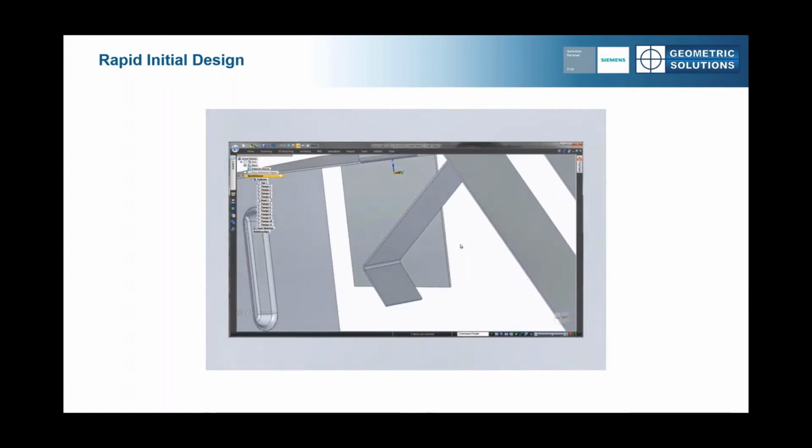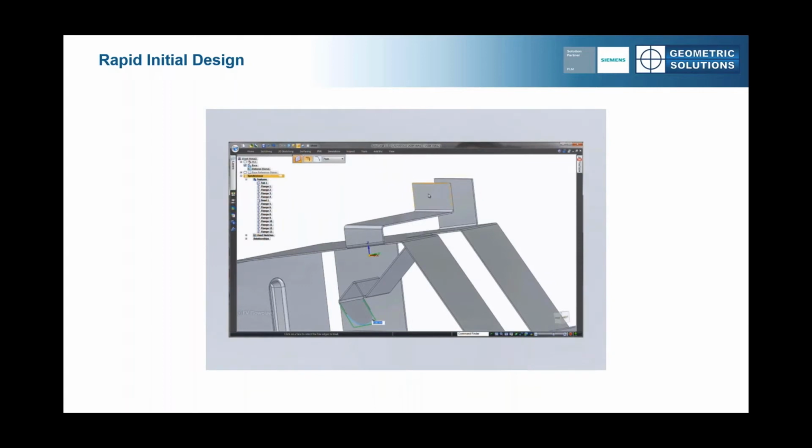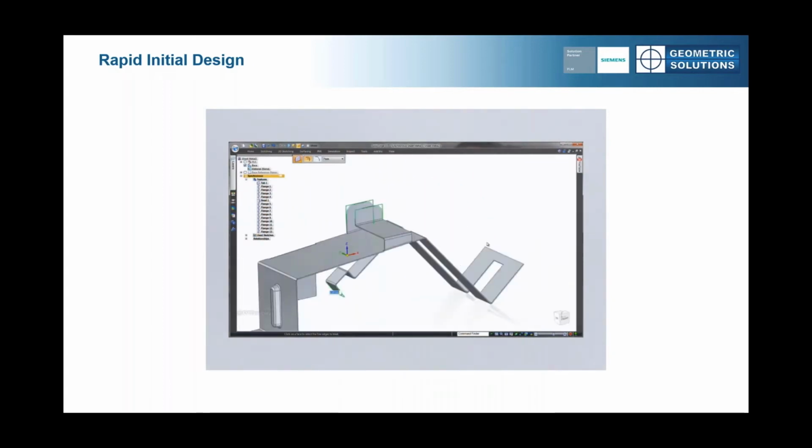Let's do the same for our retaining clip. Again, the same process, simple sketch line where we want this jog to be. And then apply that jog, dragging it out into position. Easy. Finishing up on our concept, let's get rid of some sharp edges by breaking corners. Nice and quick, click and go.